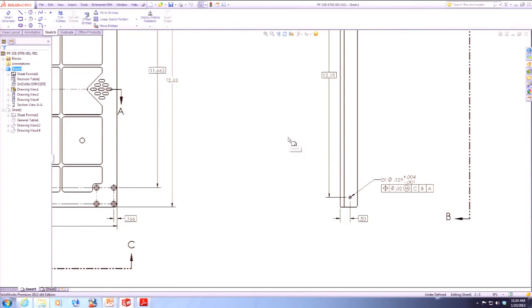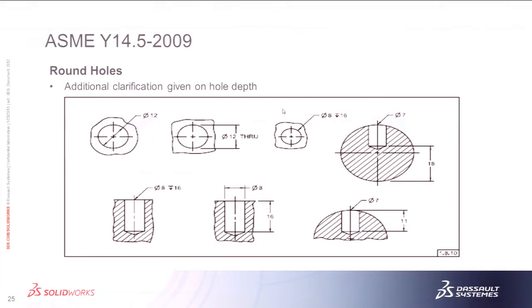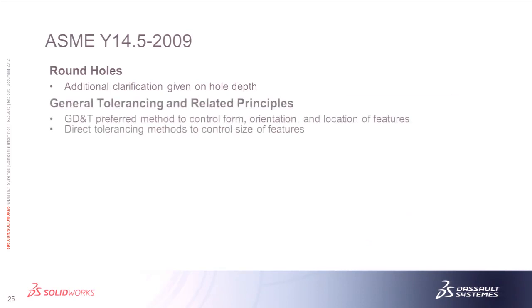And SolidWorks puts it in there automatically. You can change that. You can go into the hole callout settings, and you can customize those. It can save a lot of time. It's just a text file; pull it up, find the type of hole that you're calling out, modify it to what you want it to be, and then every time you call it out after that, it's going to be correct.